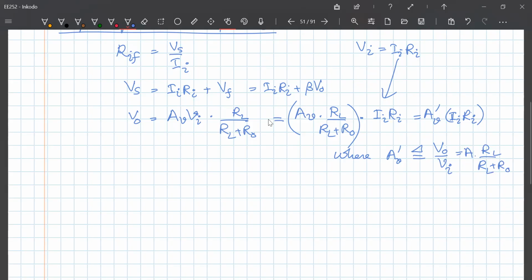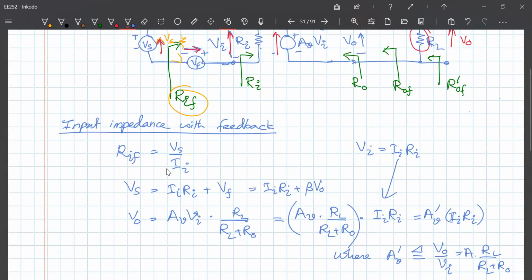When the load is connected, there is a current through it. Right. So therefore, I now have an expression for V out, which I can put here, which can be written in terms of Ii Ri, and therefore there's another Ii Ri here. So therefore I can completely replace this Vs in terms of Ii. Okay, so that I can get an expression like that.